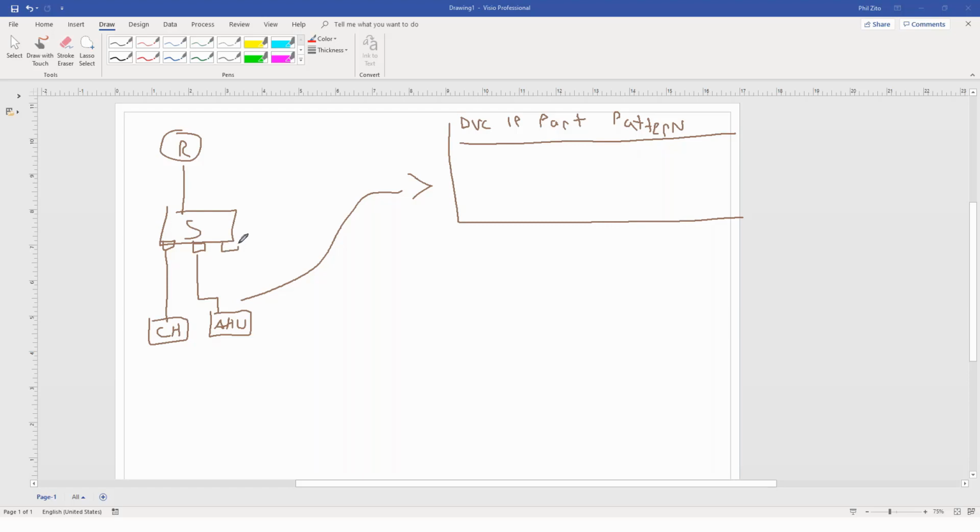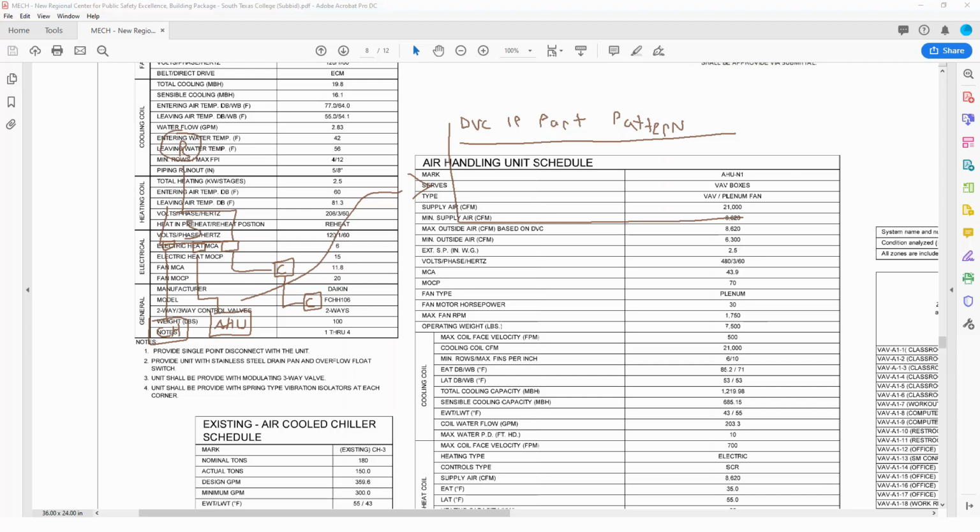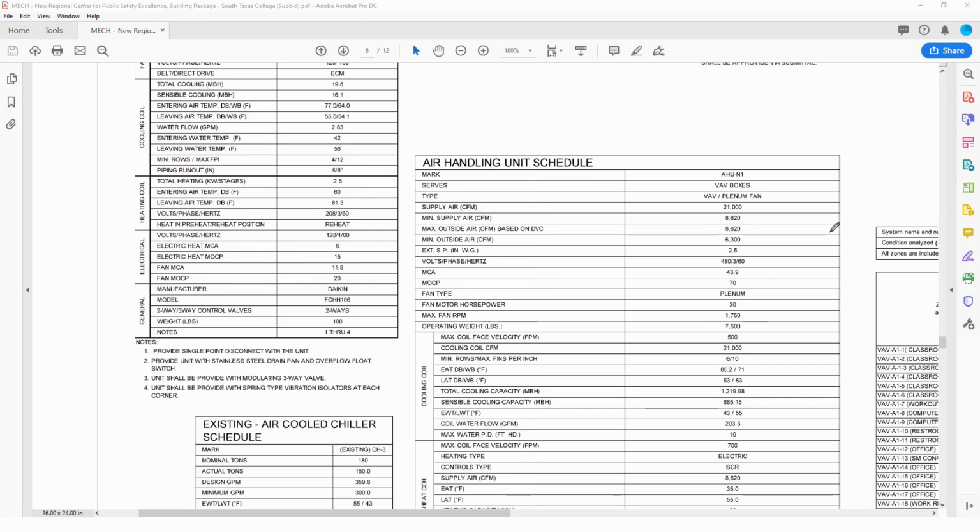And then we go and lay out our bus, from controller to controller. And what I recommend you do here is that you look at your mechanical drawings and you figure out where this switch is going to be sitting. Usually it's in the IDF or MDF. So if we go back to our drawings, we can find, let me clear this off real quick. Erase all that. Go back to pen.